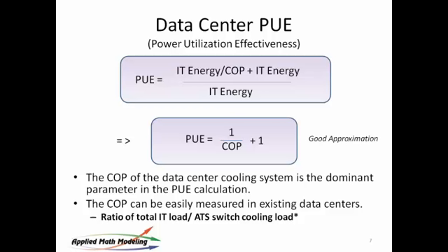Yes. So I know that there's a lot of discussion in the industry right now about PUE, how to measure PUE, and what the components are that go into PUE. And people do manipulate this relationship to their advantage sometimes, to make it look good. But I would encourage you to start here. Start with just measuring the power going to your cooling system compared to the IT load in the room, and then use that as a primary metric to get COP and see what this number looks like.